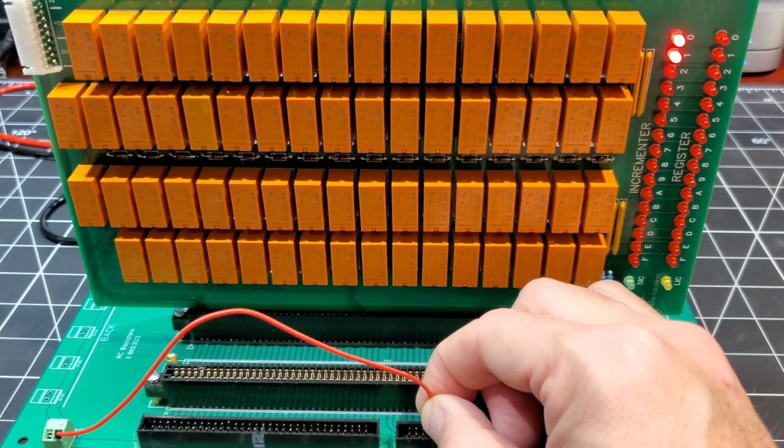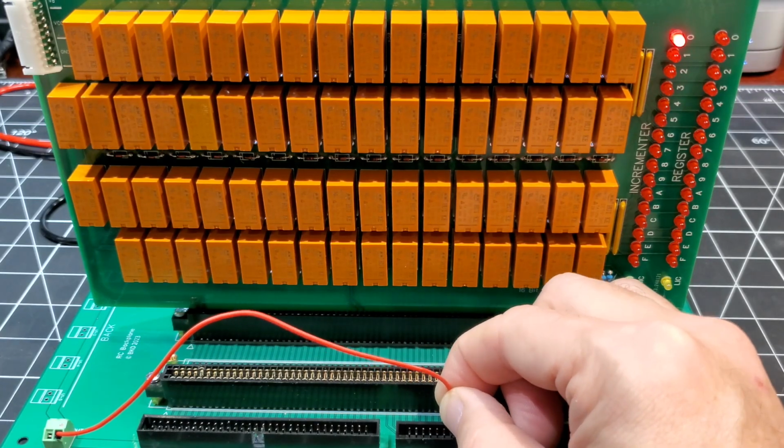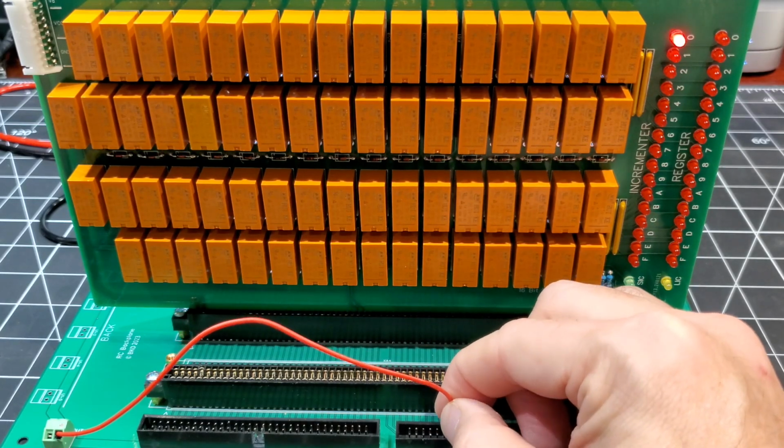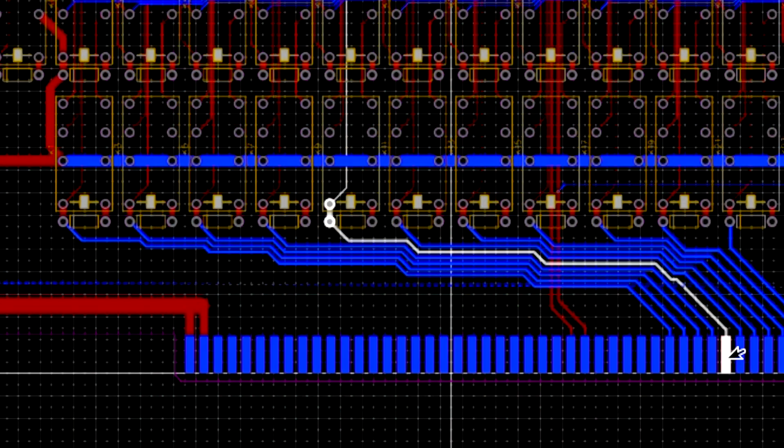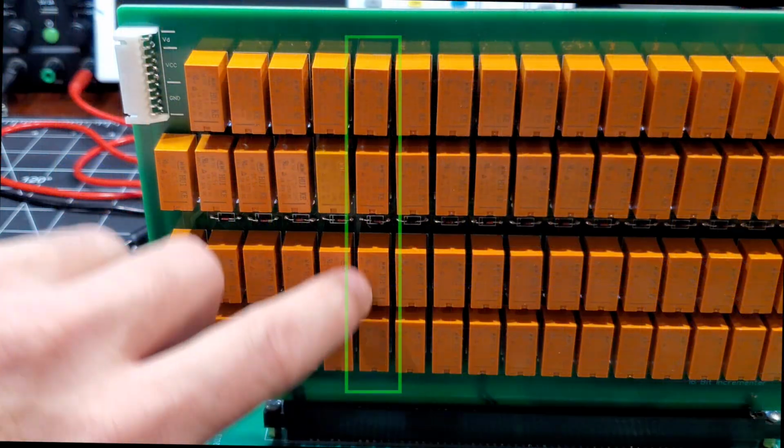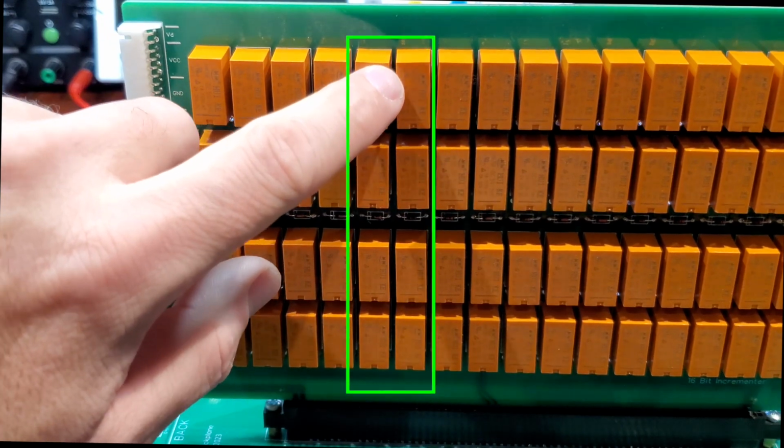So it wasn't too long before I ran into yet another problem. And this time around, it was with pins 4 and 5. Applying power to those address pins should have activated the relays, but nothing was clicking.